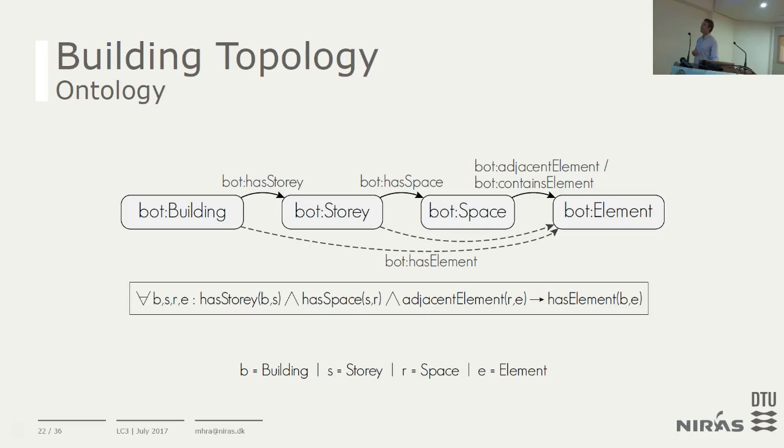And that brings us to the Building Topology Ontology. Whereas IFC has 1,580 classes, some of them describing parts of a building, some of them describing something with economy, some of them describing what a unit is, which is also described in other ontologies already existing. We're down to 4 classes, a building, a story, a space, and an element, and then we have these 5 relationships.